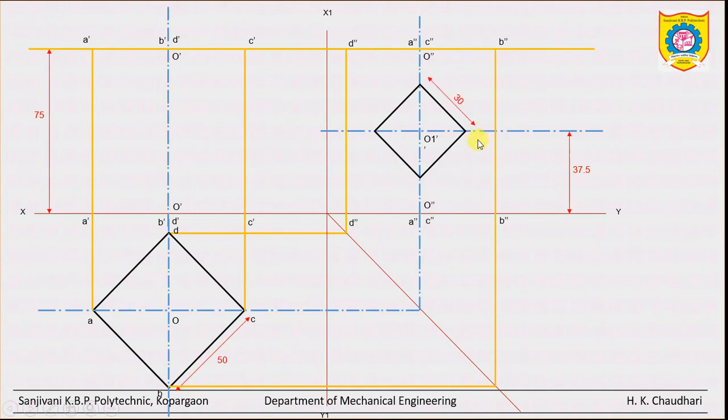Clear? Now our aim is to draw this horizontal prism into the front view and the top view. First of all, just label the corners 1 double dash, 2 double dash, 3 double dash and 4 double dash, in this way. Now extend this axis in the front view.